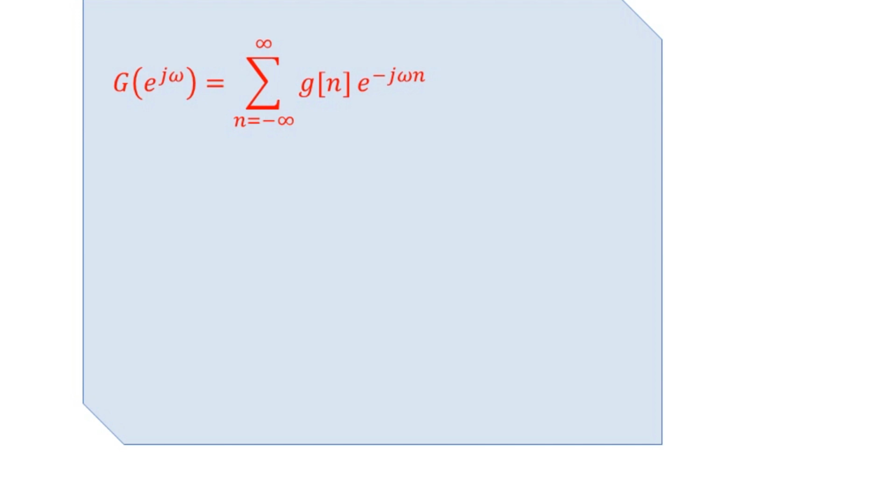So then it is assumed to provide a reasonable estimate of the Fourier transform. Here we have capital G of e to the power j omega of the discrete time signal g of n. Now such a Fourier transform version of the windowed finite length sequence is further evaluated at a set of capital R discrete angular frequencies equally spaced in the range 0 to 2 pi for the angular frequency omega by computing its R point discrete Fourier transform, that is DFT.